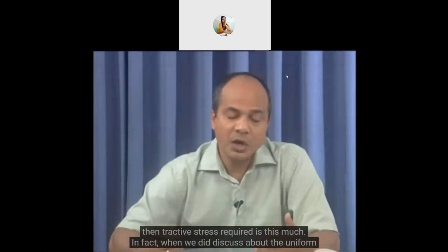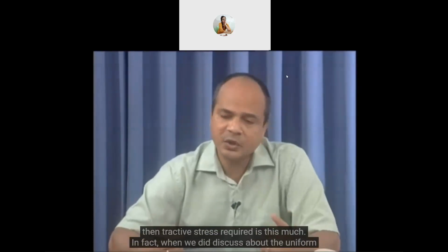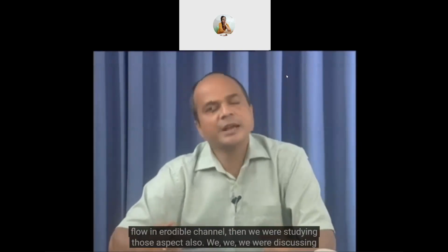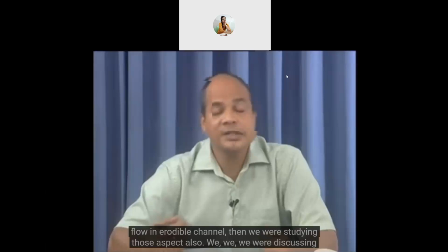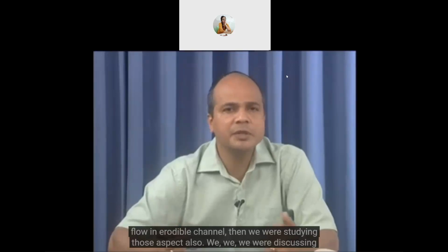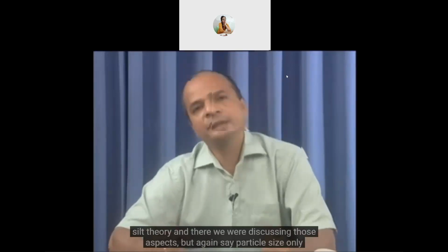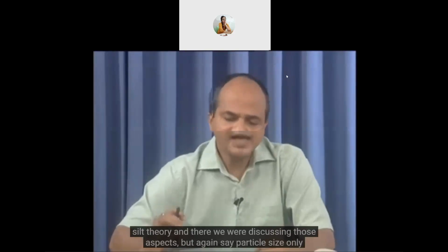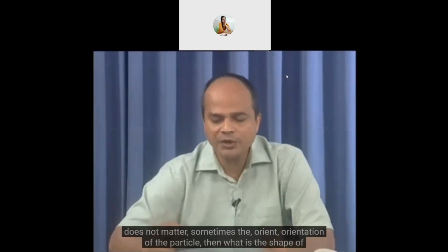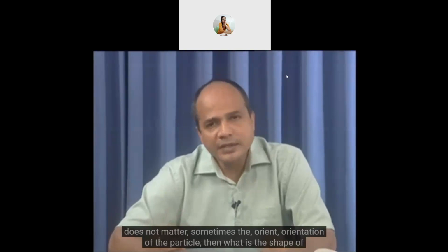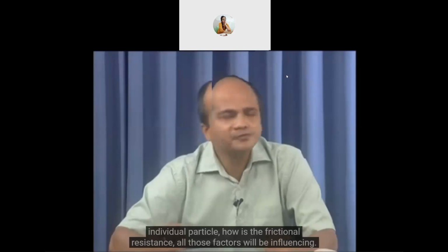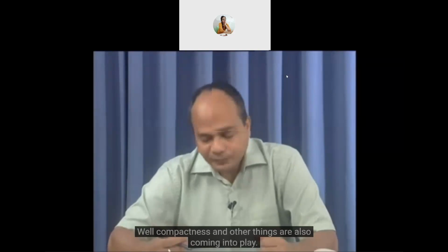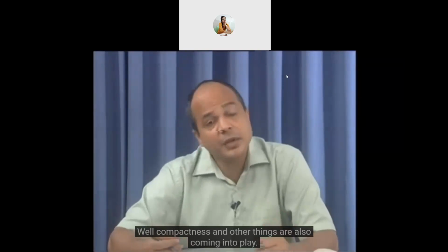In fact, when we discussed uniform flow in erodible channels, we were studying those aspects also. We were discussing Shields theory, and there we were discussing those aspects. But again, particle size alone doesn't matter. Sometimes the orientation of the particle, the shape of the individual particle, how the frictional resistance is, all those factors will be influencing. Well, compactness and other things also come into play. So like that,